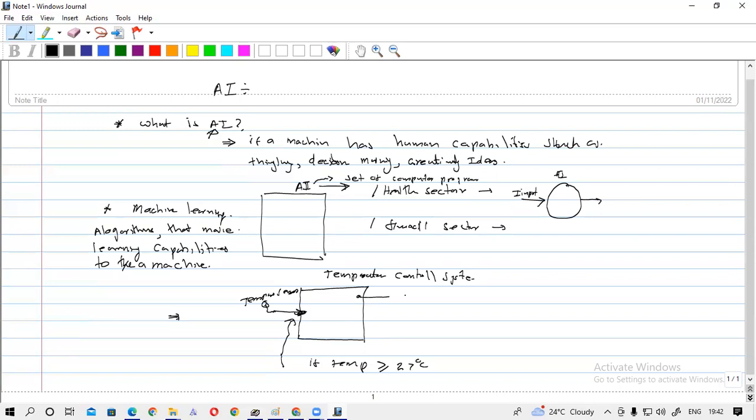Okay, using the relays. I think you can remember the wiring diagram. Using the relays, you can give the power to the AC machine, and the relay can be controlled by a small voltage, maybe around 5 or 3 volts, provided by this controller board. So we can say that.